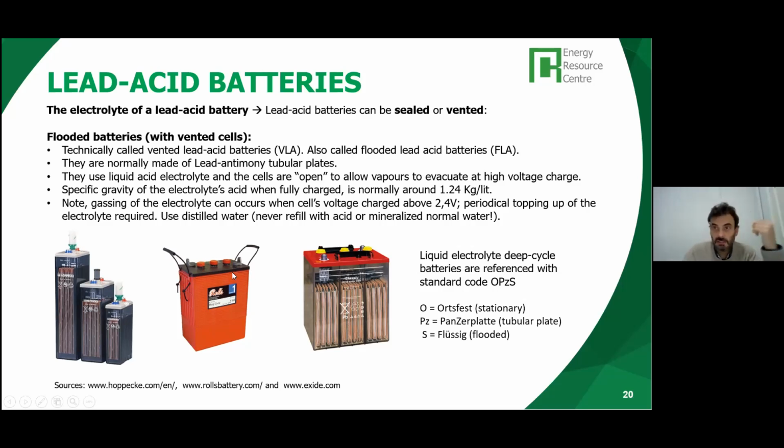So this has advantages and disadvantages. The advantage is that we can top up the electrolyte when necessary, so these batteries can give higher performance than the sealed ones. But at the same time, if we can access the electrolyte, we can access the acid, which can be toxic and dangerous. So we have to think about who is going to do the maintenance of these batteries, under which conditions, etc. Health and safety aspects are very important. And remember, these batteries can discharge large amounts of current.